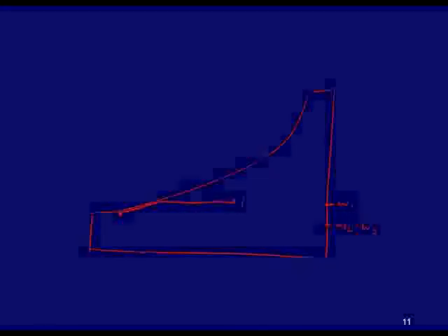We'll reheat it back to 20 degrees along a constant absolute humidity line to state 3. So this will be state 1, state 2, and state 3, and I think you'll find that if we go up to 20 degrees, the relative humidity there will be approximately 50%.